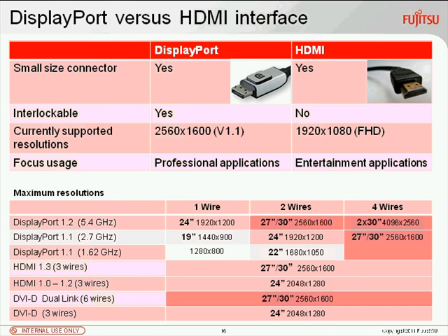And just here on this slide, I want to compare with HDMI, because some already asked me, why don't we use HDMI? Why don't we use only DisplayPort? Why do we need both? Both interfaces have one big advantage, a small connector. So much smaller than VGA and much smaller than DVI. So the advantage is you can bring it on a notebook, you can bring 4 DisplayPort connectors on a workstation graphic card. So this is a big advantage, especially on the PC side.